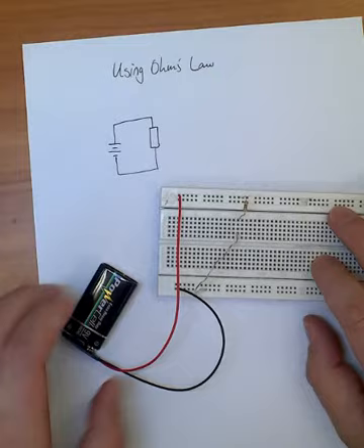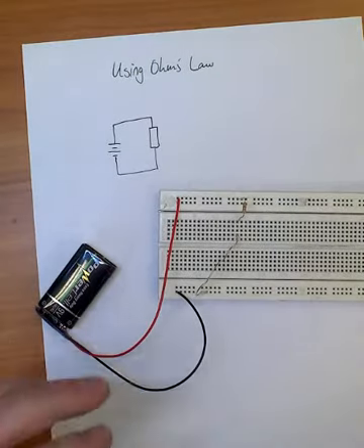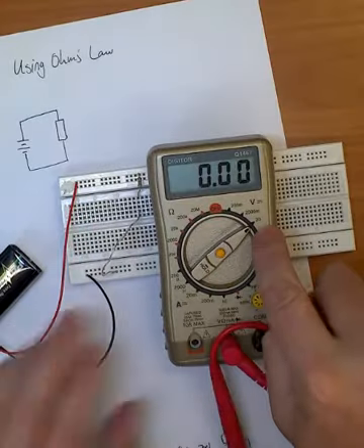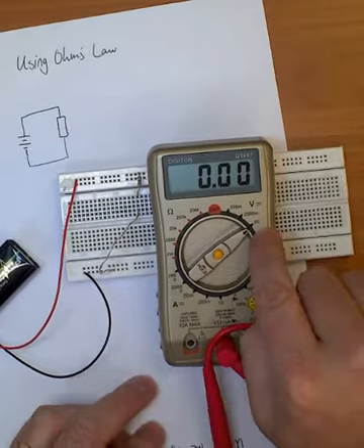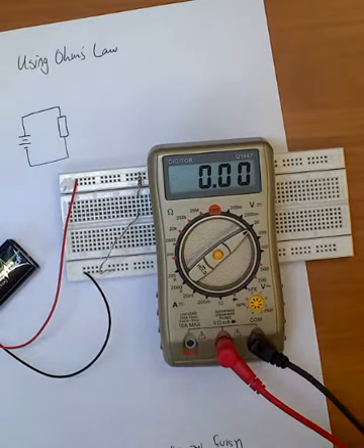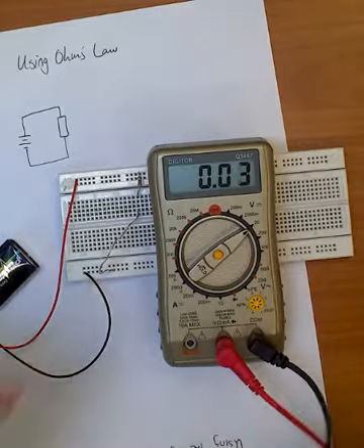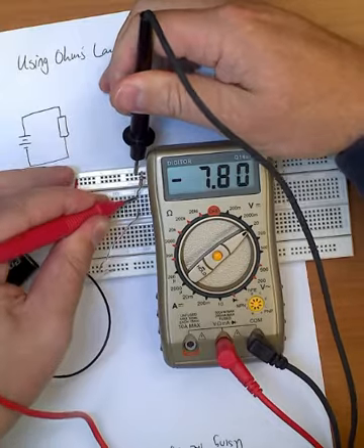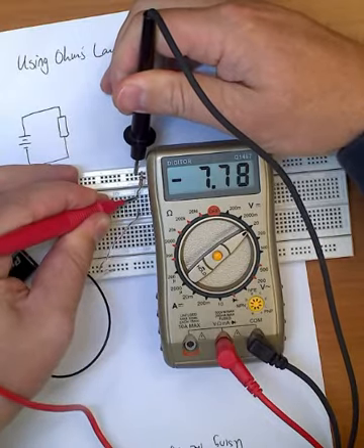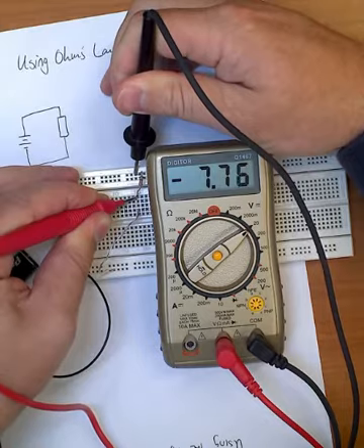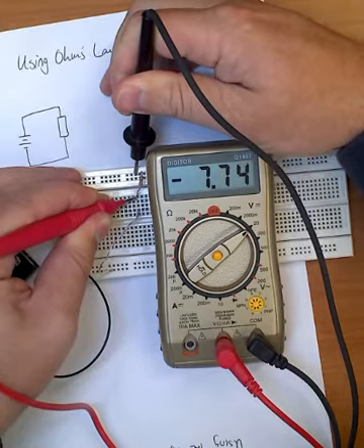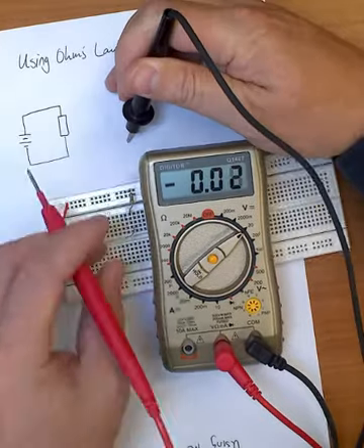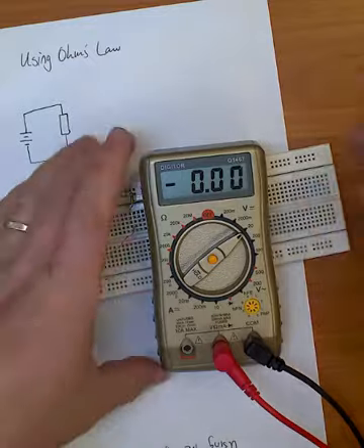So firstly I'm going to measure the voltage across my resistor. So I put it on, it's a 9 volt battery, so I'm not going to expect any more than 20 volts. And I can see that I've got the probes on back to front, so we've only got 7.7. Oh, it seems to be running the battery flat. I'll hurry up. We get it on 7.70. Disconnect it. 7.70 volts.